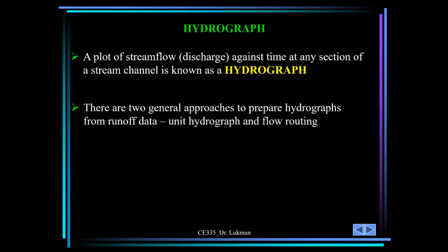That's why we call it unit, because everything will have unit there. If we can have this hydrograph, the runoff generated by this unit amount of rainfall in a unit duration, then we can derive another runoff of another duration, if you have a 2-hour storm or any other hour storm, from this unit hydrograph.